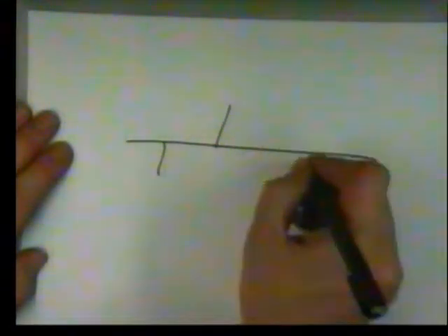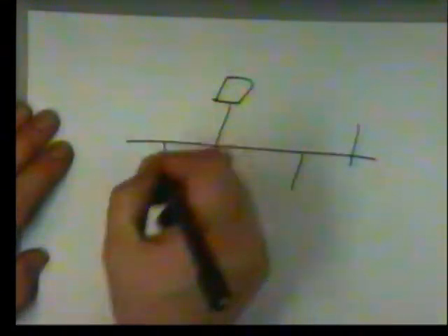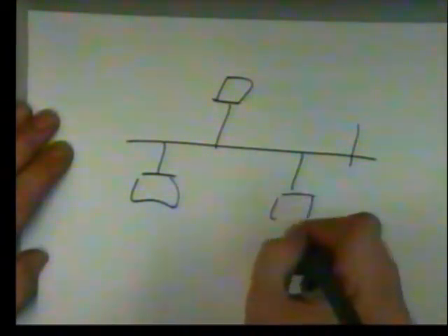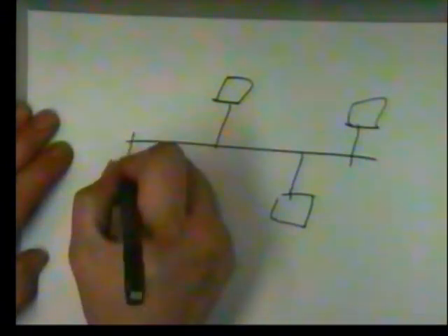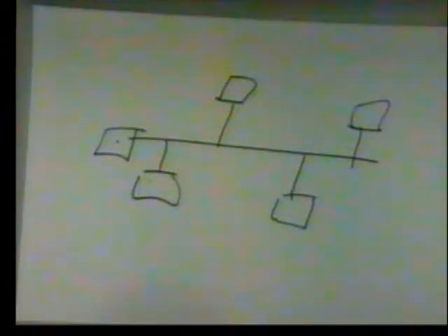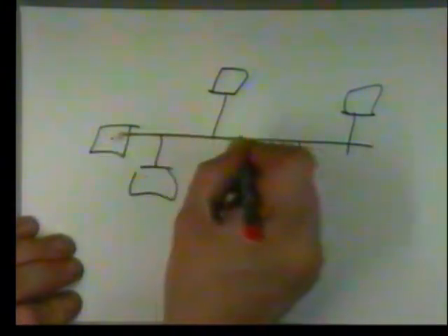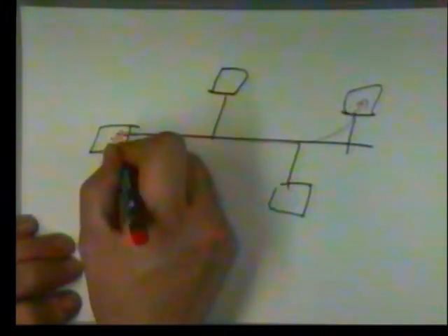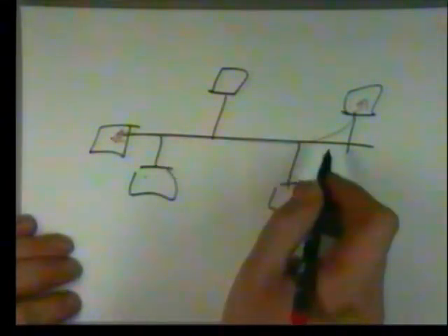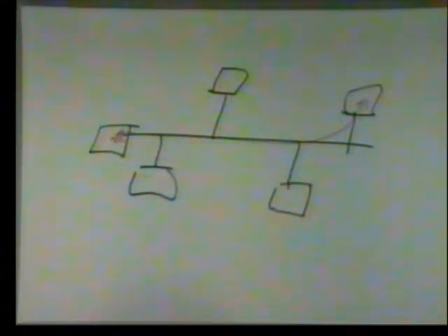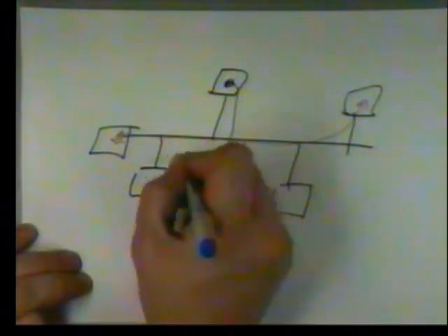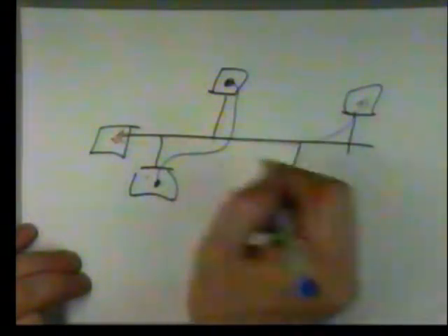So let's assume we have a network and we've got loads of users on this network, be it a bus structure; it could be true for a ring or for a mesh structure. Every user has an address with a traditional LAN, and whenever a message is output onto the network, it's always routed to a particular user. So the role of the network is merely to act as the carrier, taking the data from one user over the network into another user. There is always the concept of a link. You don't have that with CAN bus.